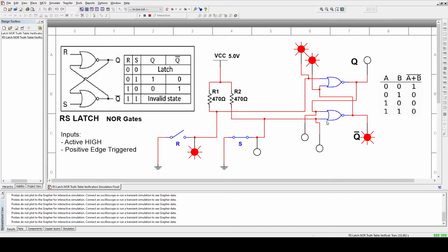Now over here I have what's called a pull-up system of resistors. So here's a VCC, and VCC we tapped at 5.0 volts, so that's good. There are just some current limiting resistors. So we go the current pathway for this input. You see that this point here is connected to this input right here. It's the R for reset. Now the other one, S for set. This input is connected to that.